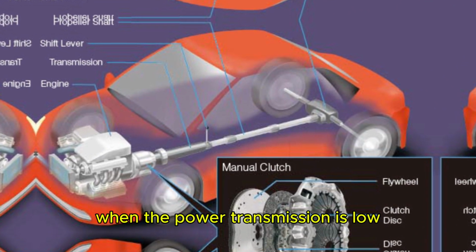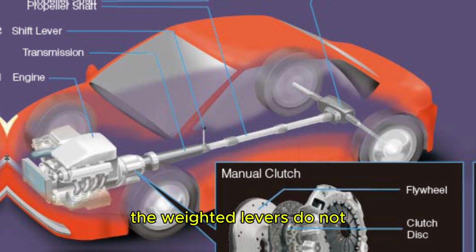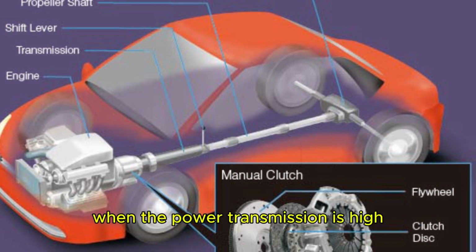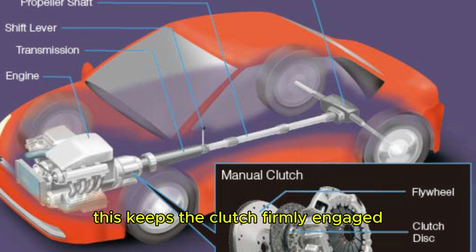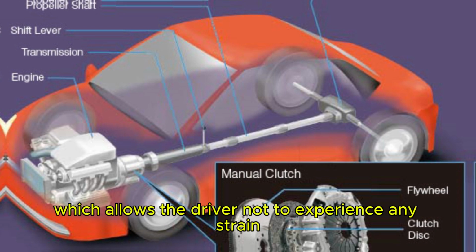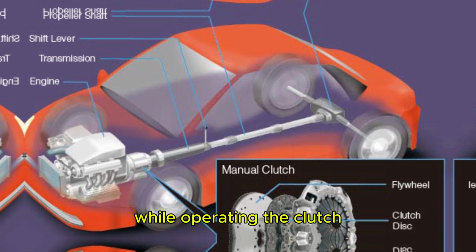When the power transmission is low, the springs keep the clutch engaged. The weighted levers do not put any pressure on the pressure plate. And at high engine speeds, when the power transmission is high, the weights fly, which allows the levers to exert pressure on the plate. This keeps the clutch firmly engaged. The springs in these types of clutches are less stiff, which allows the driver not to experience any strain while operating the clutch.